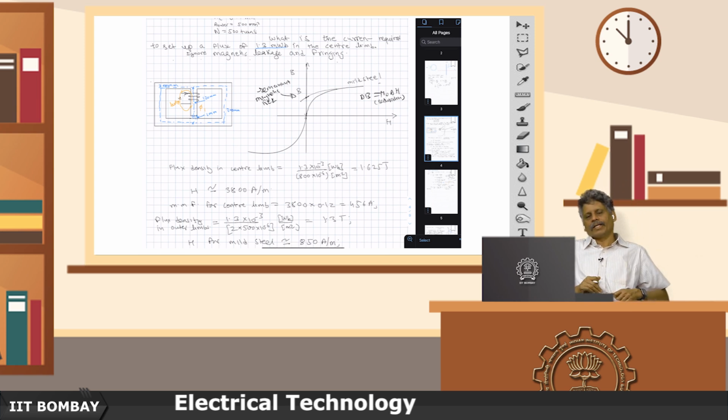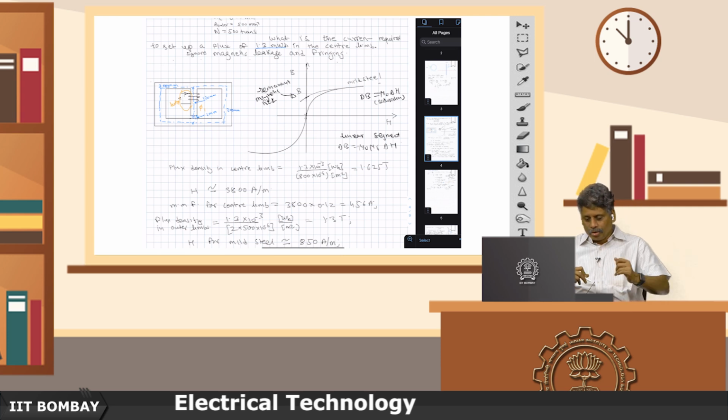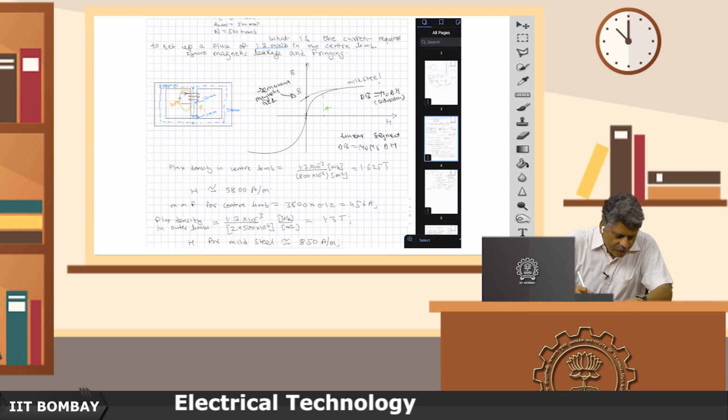and this is the saturation part where you have delta B equal to mu 0 times delta H. But in the linear segment, when it is not saturated, which happens initially, then your delta B slope is going to be mu 0 times mu r, and somewhere where it starts changing, and different definitions are available, but somewhere where the angle is, let us say, close to 45 degrees, or another definition is project the saturated part, wherever it intersects, bring it down.